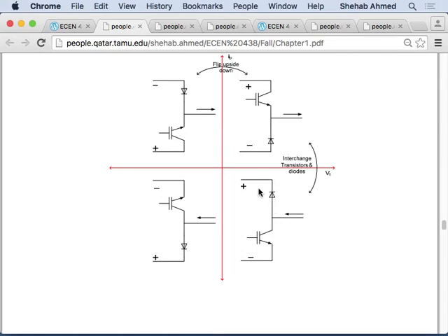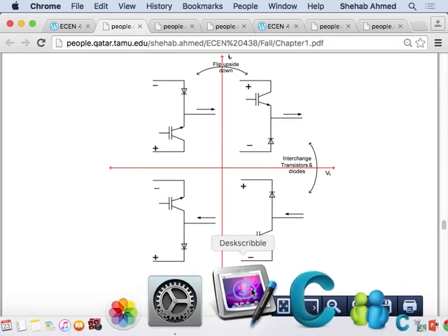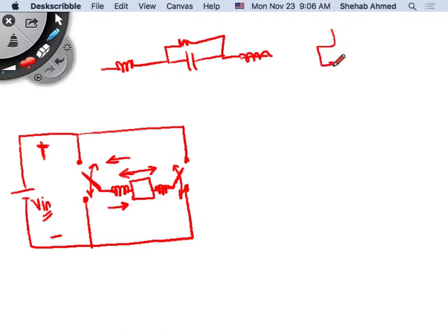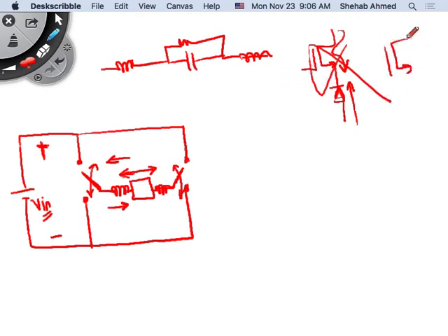If you put them in series, then you will have a switch here and a diode here. This wants to push current this way, this wants to push current this way. It will not work, right? So the only way to combine these would be to put the switch and the diode in parallel. If we do that, then we can allow current to flow this way in a controlled fashion, and this way in an uncontrolled fashion. Okay, but at least I can have current flow in both ways.